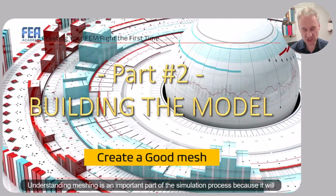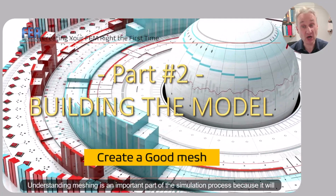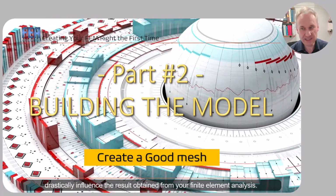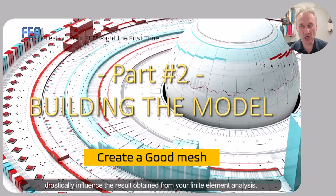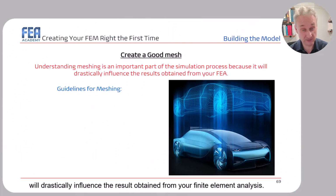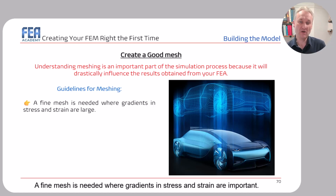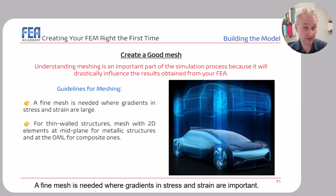Understanding meshing is an important part of the simulation process because it will drastically influence the results obtained from your finite element analysis. Let's have a look at the major guidelines for meshing. A fine mesh is needed where gradients in stress and strain are important.